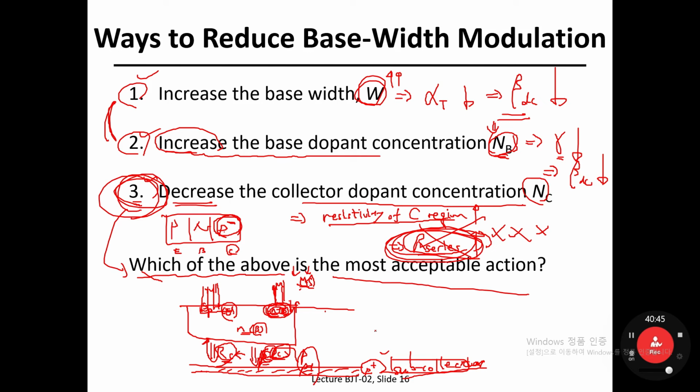Okay, so this increase in R series can be avoided. How? Yes, a very heavily doped sub-collector can be connected electrically in parallel to the p-type collector region. So this is the holistic view of the cross-sectional view of BJT. Not top view, but cross-sectional view. So emitter, base, collector, and sub-collector.